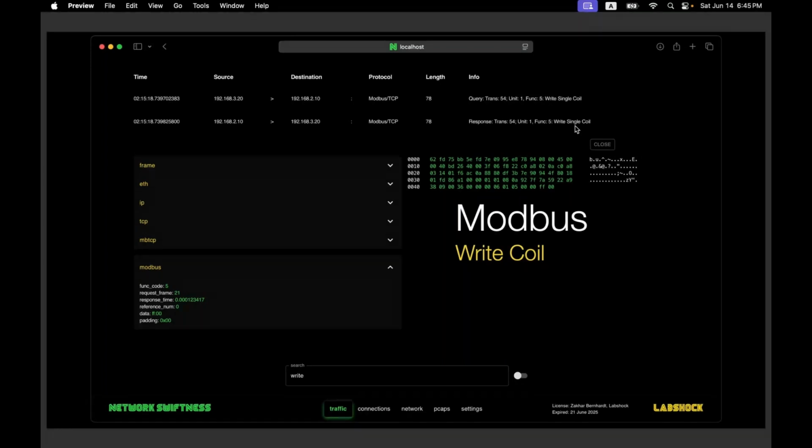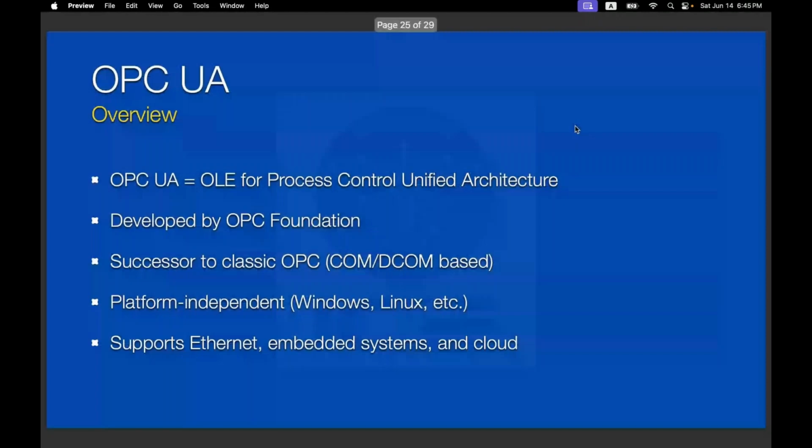And how to secure this Modbus is a big question, and this is why we have OPC UA, more secure protocols which will replace the old ones. With modern systems and architecture, I strongly recommend using modern protocols, not sticking to Modbus, and only after that thinking about how to secure it.